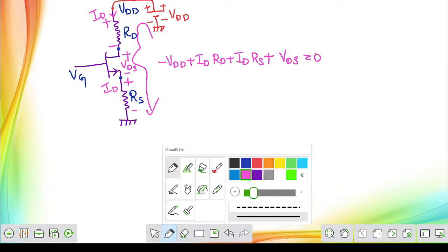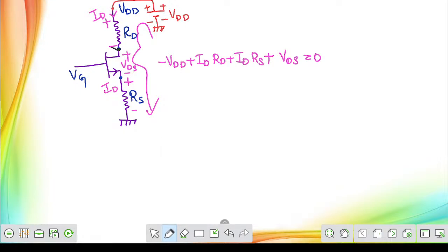The next thing you must carefully understand is VDD is different, VD is different. VD is the terminal voltage of the MOSFET. I made a mistake in the symbol representation, sorry. Put one more line here. Everything will be clearly given, but you should remember that the terminals of the MOSFET can be separately considered as VD, VG, VS. Some of you will consider this as VS, but that is wrong. You should not take this as VS. Only the terminal of the MOSFET can be treated as VS.